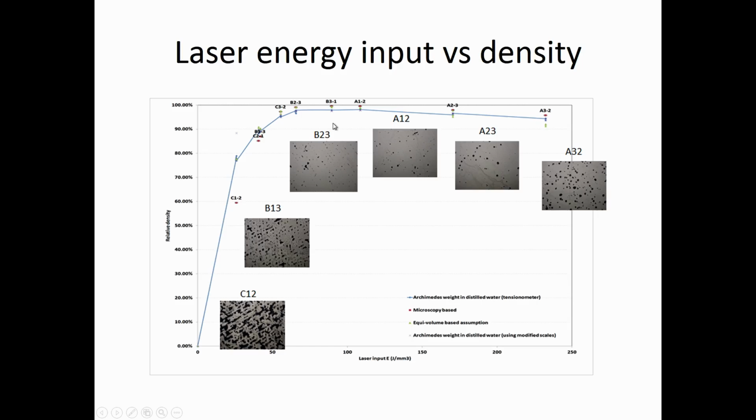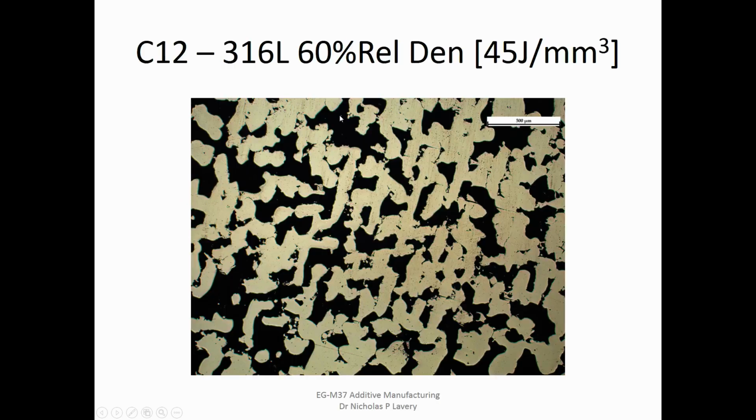And that was relatively easy in the old days because we didn't have that much laser power, and we were getting much larger overall porosities. And nowadays, instead of that sort of best bet 1%, the best bet is almost 99.999% or even 100% dense. And it's more difficult to pick out where the optimal is.